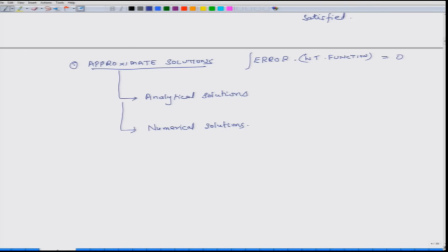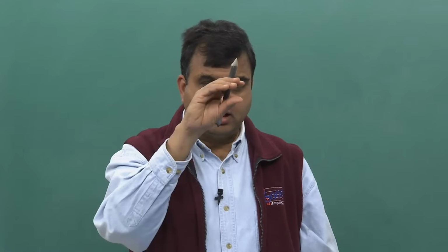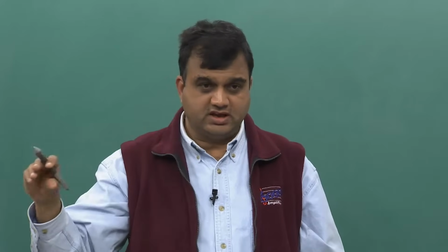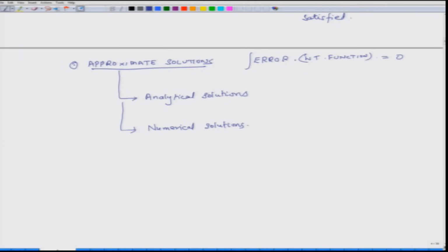So, point by point the error may not be 0, but the error may be a little bit high at one point, a little bit low at another point, and if you add up all these errors after weighting, that is the integral, right? That is the integral. This is omega, it represents the domain, or domain means the area of interest, the region of interest.